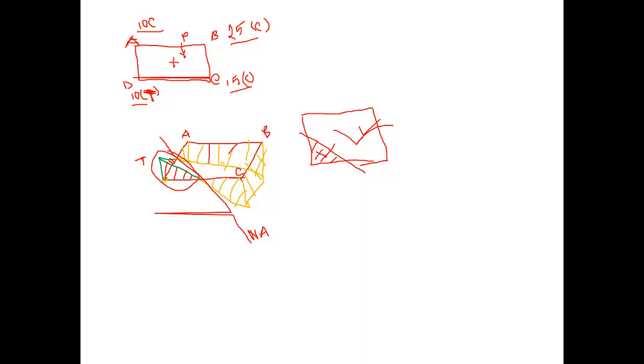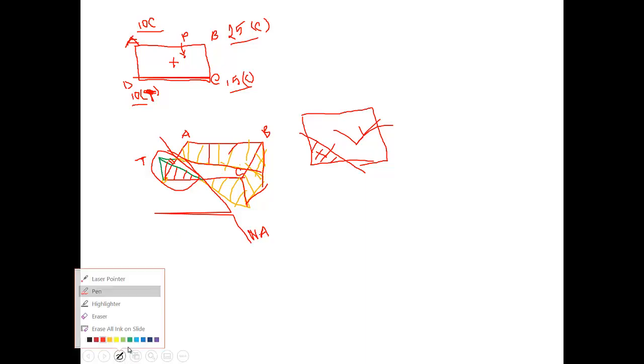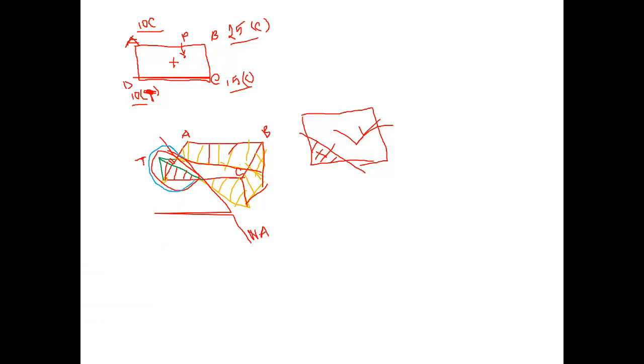So this portion of the footing is having tension. Now the question is how did they calculate this? They calculate this stress from the combined stress calculation. There are certain formulas or methods to find out the stress at each corner. Then if you draw this, you'll find that these portions are in compression, but only this portion is having tension. So that's why this portion is not effective in the footing, right? This portion will be the inactive portion in the footing.